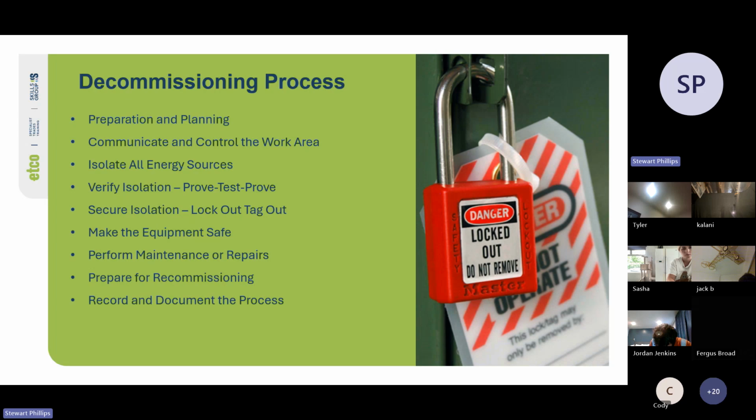The process for discharging a capacitor is you take an appropriately sized resistor and short out the terminals of the capacitor. One way of doing it is you get a nice big thick iron rod, grab a glove, and then take the iron rod in your gloved hand and put it across the capacitor terminals. That is one method. It's not the only method, but do not ever try and use your pliers. There is a high chance you could damage your pliers doing it that way.